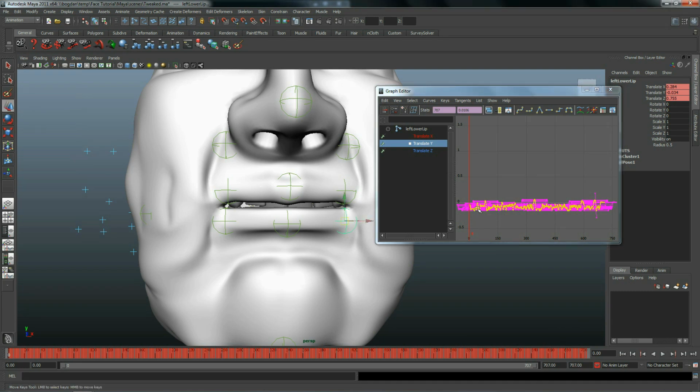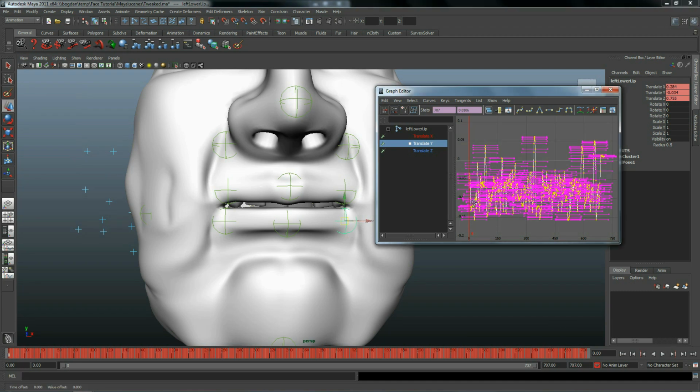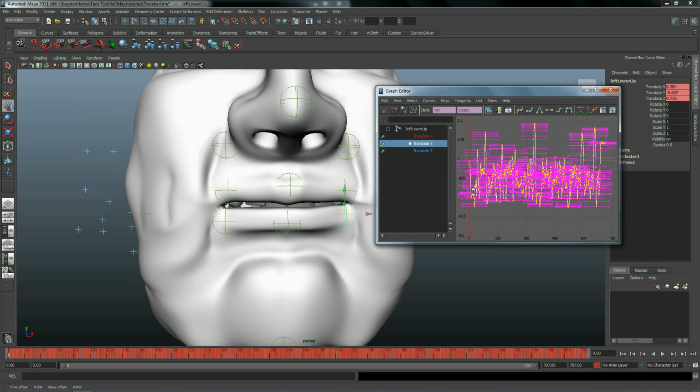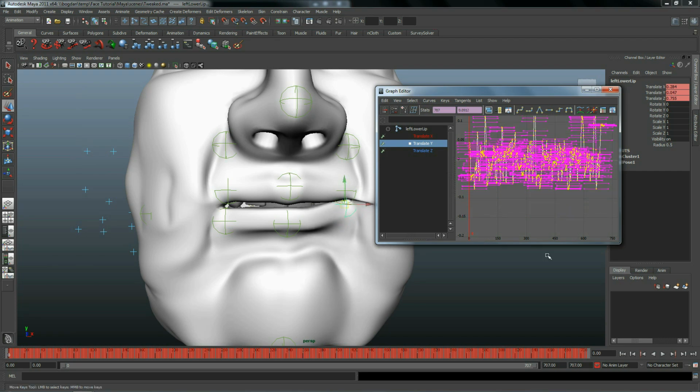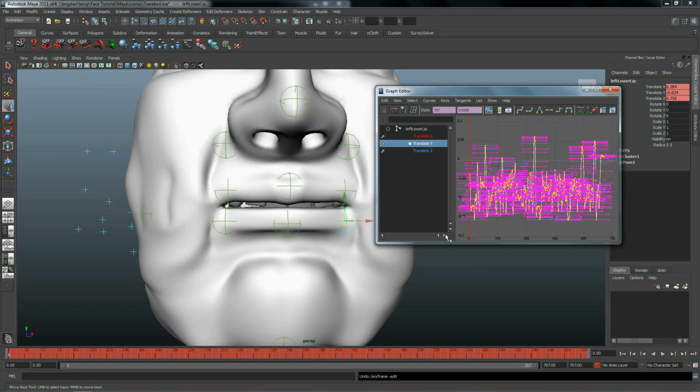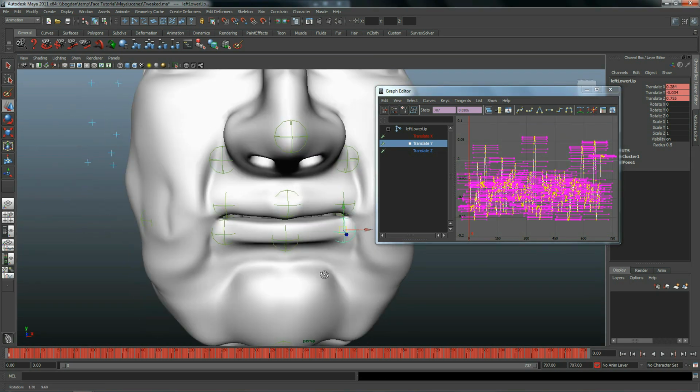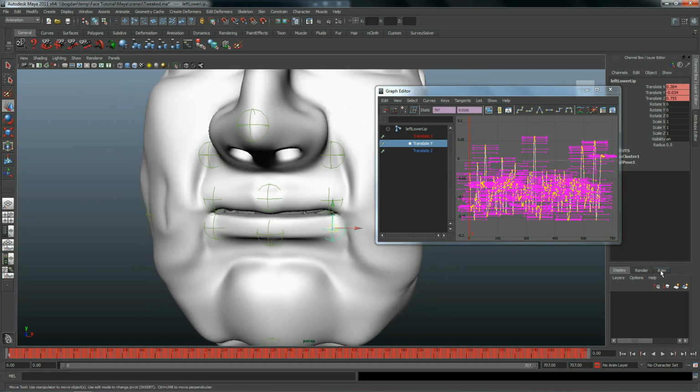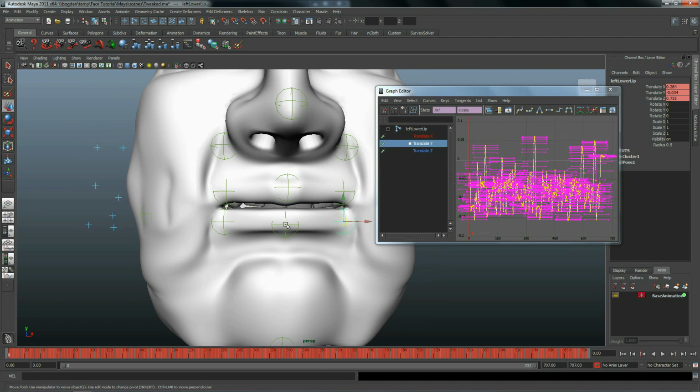The problem with this solution is that we will destroy the original data, making it hard to revert the process later on. Option number 2 involves using the feature Animation Layers. This will add animation on top of existing data, allowing us to disable the layer and its changes at any time. We can also weight how much the layer will influence the original data.